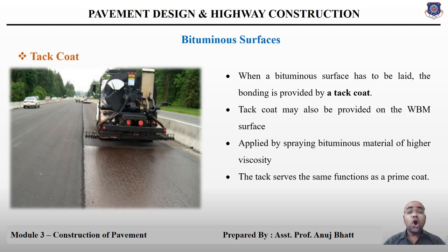The tack coat may also be provided on the water-bound surface or water-bound macadam surface which has already been treated by the prime coat. The tack coat is usually applied by spraying bituminous material of higher viscosity, like hot bitumen, at the rate of 4.9 to 9.8 kg per 10 meter square area. The tack coat serves the same function as the prime coat.